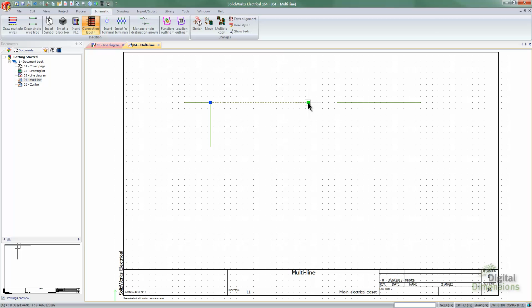The other part of Electrical is you don't need to keep track of all your lines. So if I drag one line over the top of it, it'll turn it into a single line. So I don't need to trim anything or keep track of all that. If I disconnect an intersecting line, it'll heal it back into a single wire. This is what they call smart objects, so it allows the lines themselves to be intelligent enough to anticipate what you're doing with it, so you don't have to keep track of all that stuff.